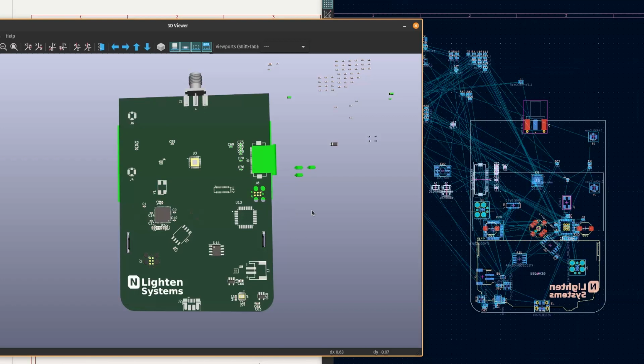Do I just have to send deltas to it? There's a whole protocol described in the documentation for this e-ink on how to do the full refresh versus just the partial refresh. It works on a simple array in memory where each bit is just pixel on or pixel off.